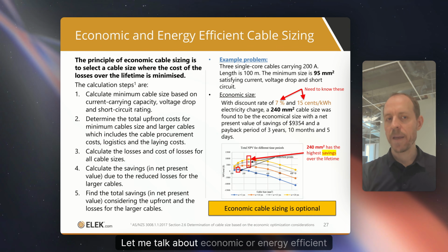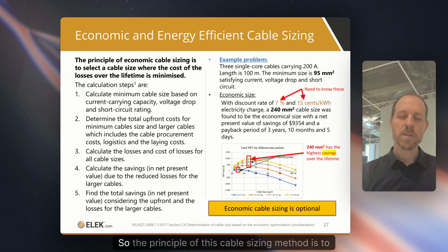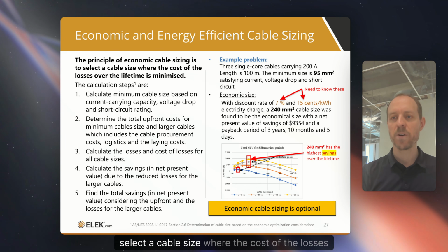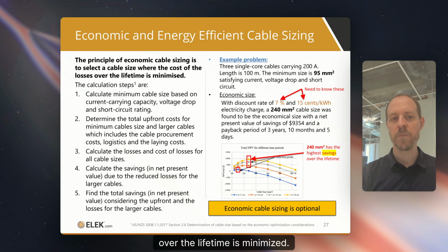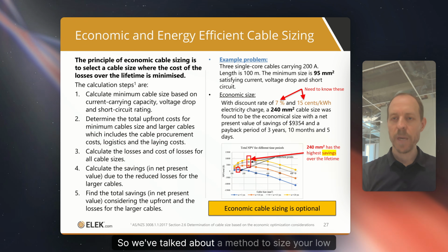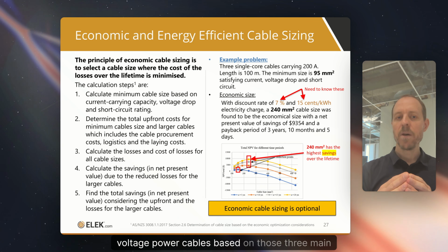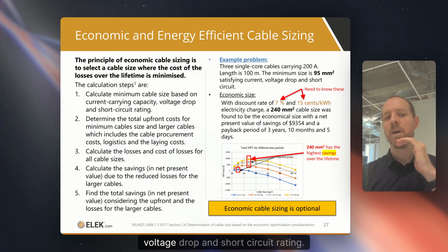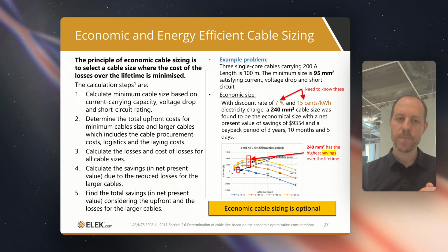Let me talk about economic or energy efficient cable sizing. The principle of this cable sizing method is to select a cable size where the cost of the losses over the lifetime is minimized. We've talked about a method to size your low voltage power cables based on those three main criteria: current carrying capacity, voltage drop, and short circuit rating. So that's what we could say is the minimum safe size.